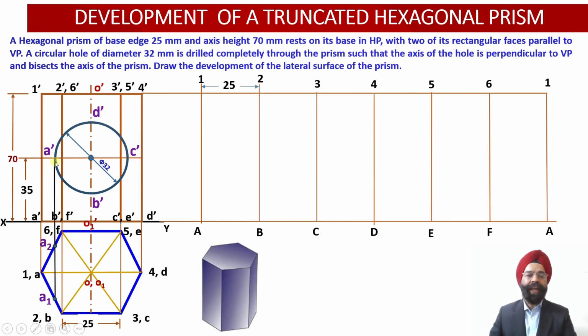Corresponding to these 2 points, A' and C', again we can check that they do not have any existing vertical edge passing through them over here. So we have to obtain the location of these 2 points A and C in the top view projections, and let us evaluate them corresponding to the front face and the rear face of the solid.